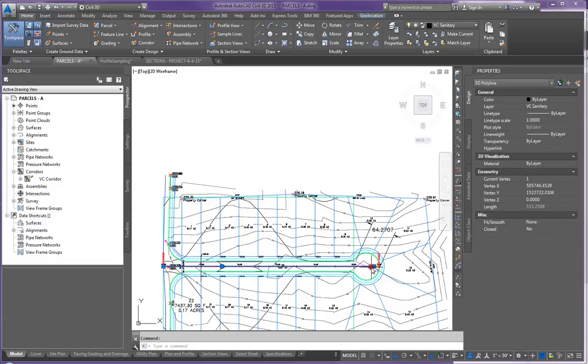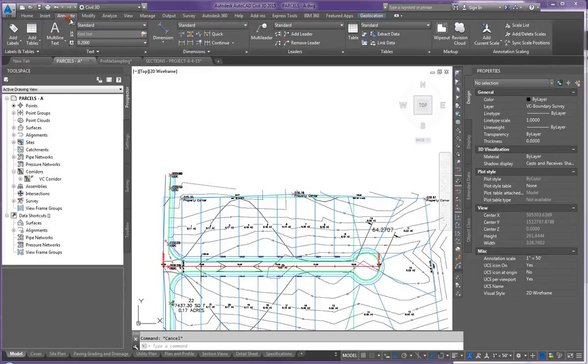And now what I'm going to do is adjust this 3D polyline, and it's going to be at 225. I'm going to start a foot below that. So it's going to be 224. And I said that I was 400 feet away. So 224 minus 400 times 0.01. I'm going to make it at a 1% slope. So this is going to be 220 for vertex 2. And then for the last vertex, I have to check what that distance is.